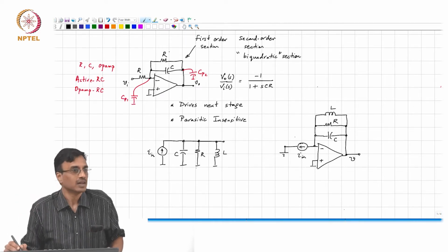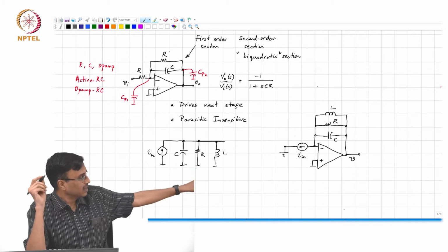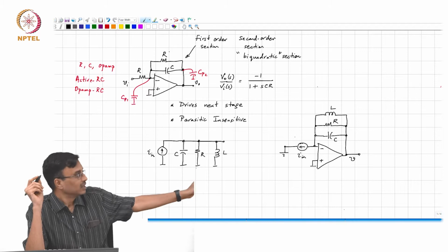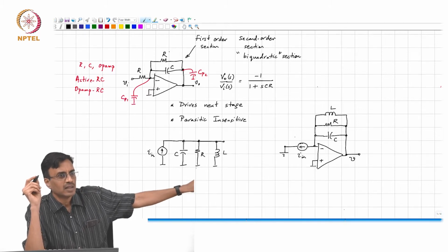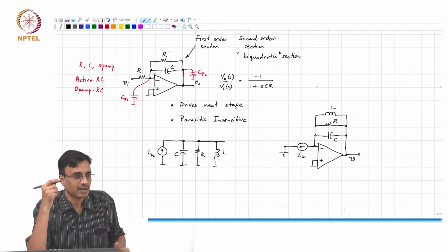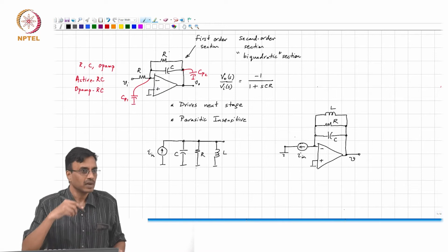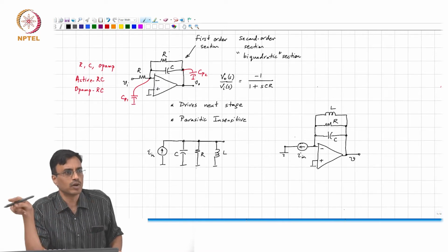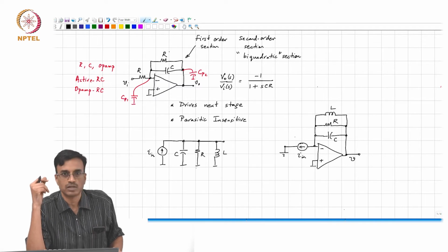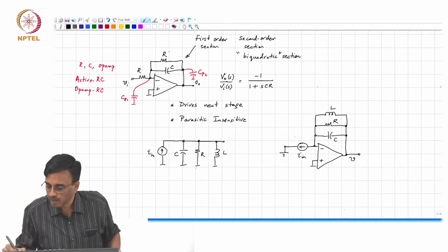Remember all that: in the circuit on the left, this current is flowing through the RLC network. The circuit on the right, also the current is flowing through the RLC network. So the voltage across the RLC network, which is band pass, will now appear across the op-amp, except now the op-amp is able to drive any load, at least in principle. So this is the band pass out.